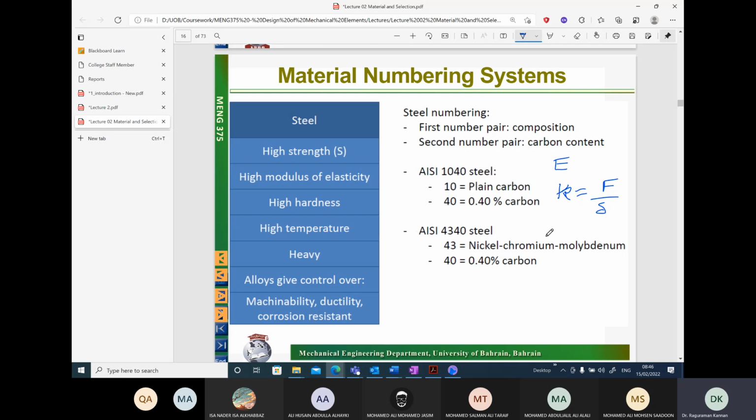So in the case of a simple axial rod, if you apply a force F, in this case we can calculate K as E times A over L. So this is the stiffness property. Okay, take this for granted. So here if the E value increases, then the K value will also increase.